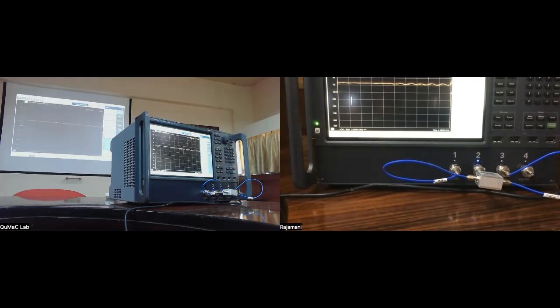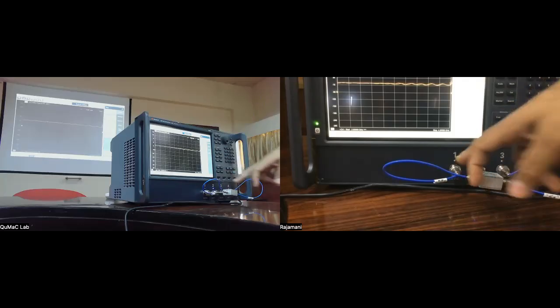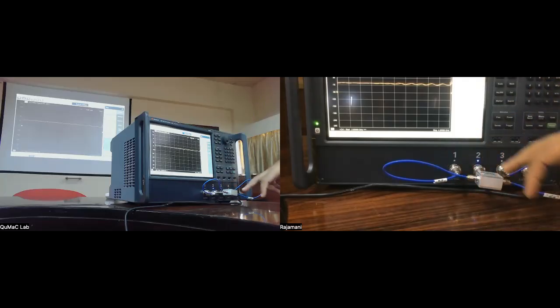You need some transmission line to feed the signal. Then that transmission line on chip has to connect to some connector like these things. Okay. So when we study these devices in detail, I will also open one of these devices and show you how this packaging is done, how you transform signal from a coaxial geometry to a planar geometry. I had passed around some boards in one of the earlier classes, right?